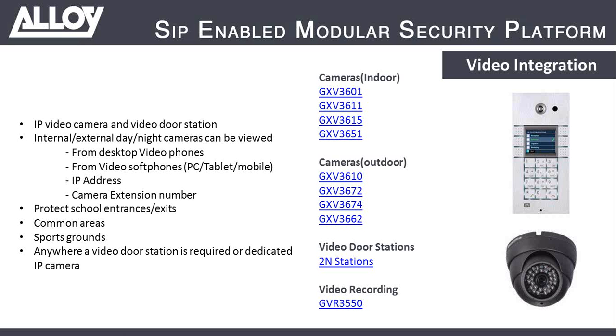But just to hit the high points here for us all, there's 4 indoor cameras, 4 outdoor cameras. The outdoor cameras are all IP65 and above. There's vandal-proof options. One of the cameras has integrated microphone and speakers. All of the cameras support the option to attach external microphones and speakers. And the really important point about this gear is that all of these cameras are not just IP, but they're SIP-enabled endpoints.